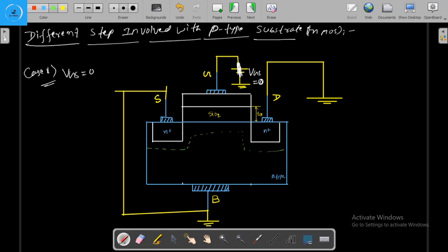And we have also seen that when an n-type and a p-type semiconductor come in contact with each other, here the positive ions will be available, these are immobile ions, and here the negative ions will be available, also immobile.